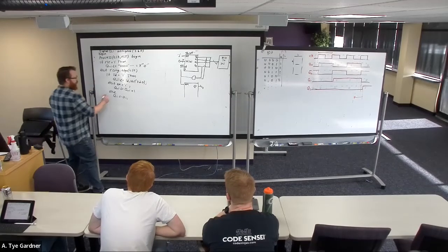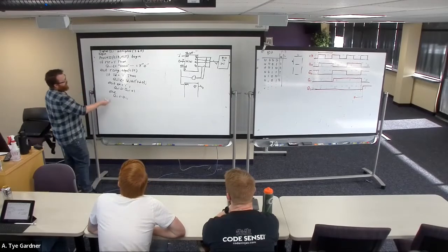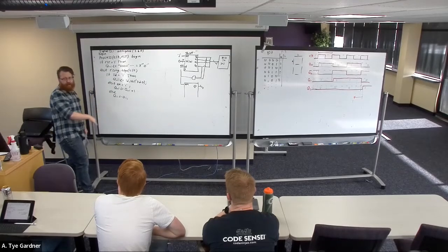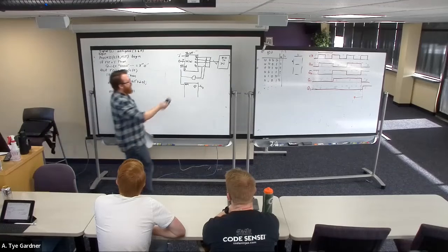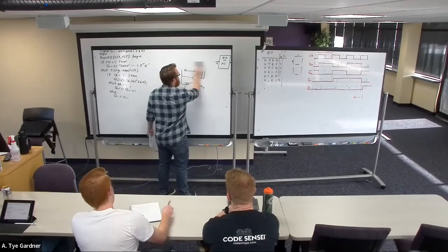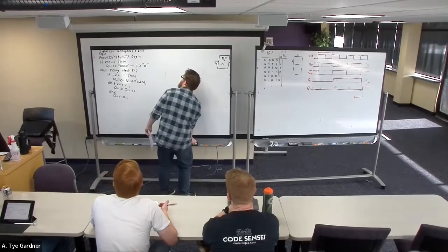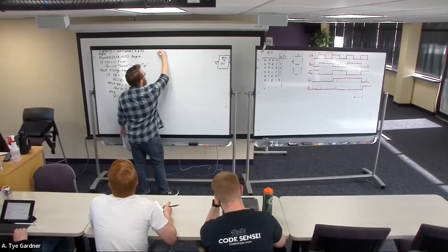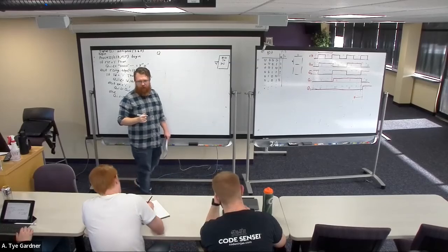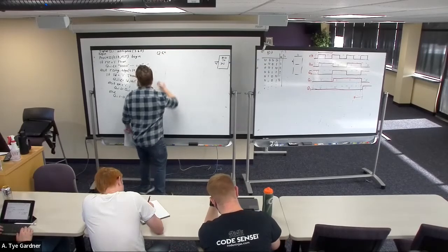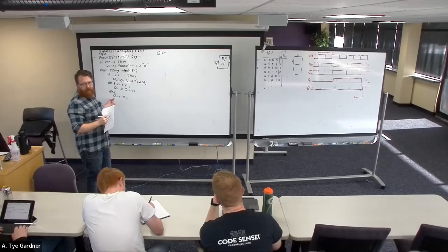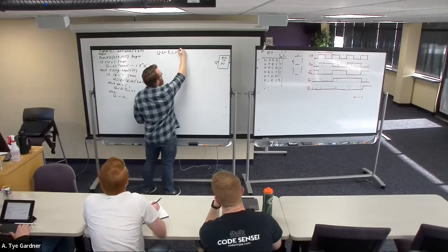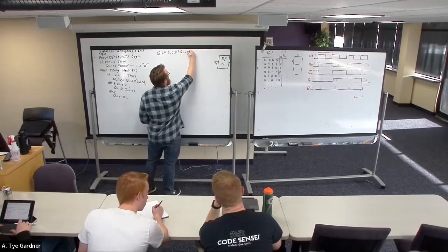Okay, then we're going to write the end if, end process. Okay, that's going to all be down here. I'm going to not write it all. And then I would come up, and sorry, I have to erase this. Let's keep this in mind though. Then I would come up after all of the ends, and I would just write Q, which is my final output. It's assigned to, well, it's going to be QI, but QI is unsigned. So I just write the standard logic vector. I have to write the whole thing out of QI.